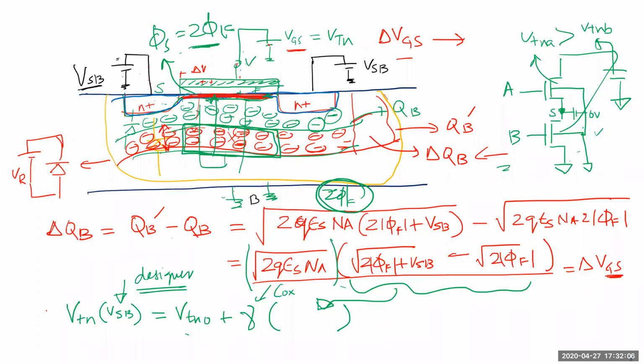So what we are doing is increasing the voltage of the source right now. So the source and the drain, you just increase the voltage of that. That means the source is now at a higher potential with respect to the bulk. When we are talking about VT, we are talking about the gate to source voltage, VGS, and we are saying at what particular VGS the channel will form, and that is with respect to the source.